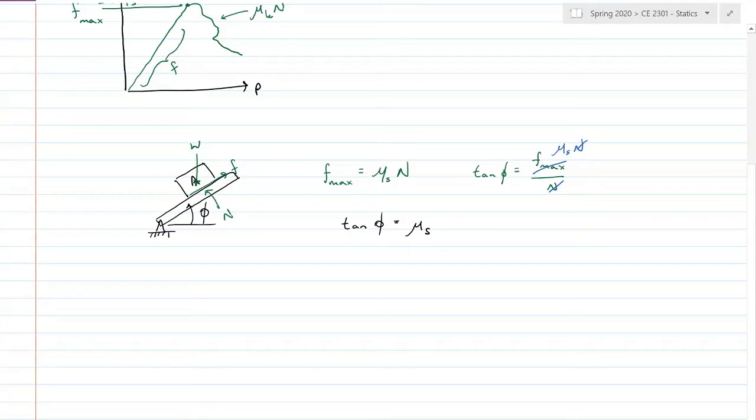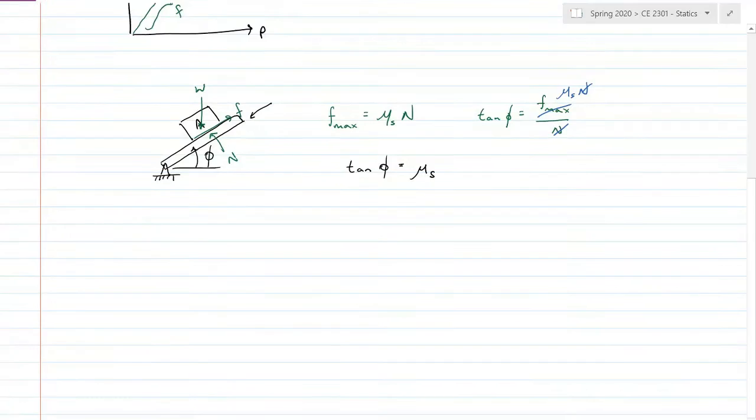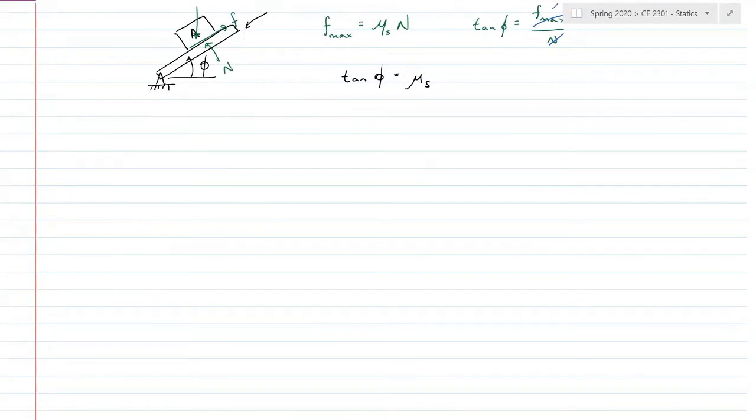Well, at some point, the friction strength, strength being the best word I can think of, is the angle that we can rotate our board until the block starts moving. And that's our friction value. That's how that's calculated in the lab, if you will. And that comes into play later on when you're doing screws and belts and some other things that you'll see again in dynamics.